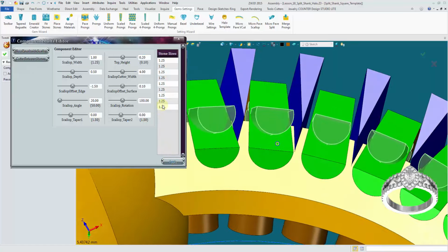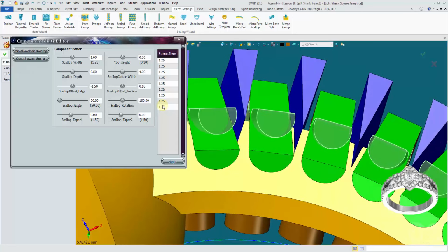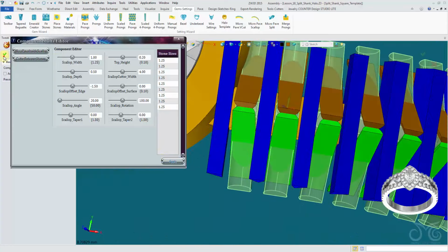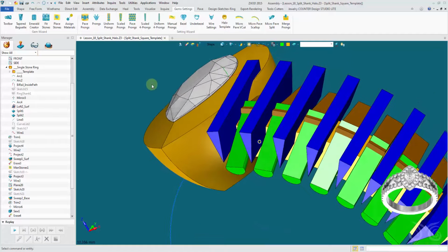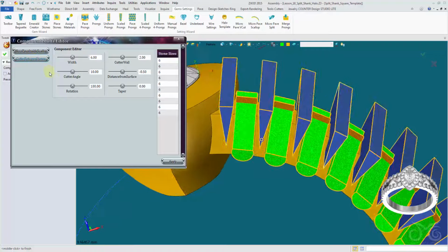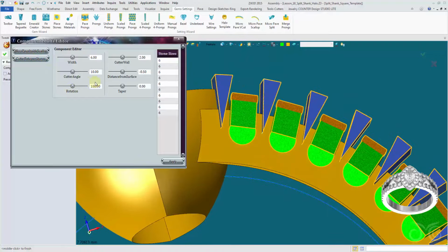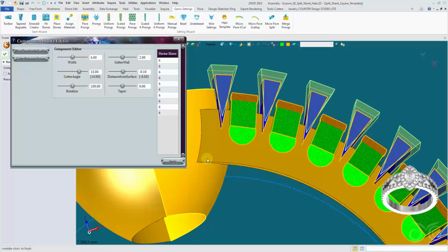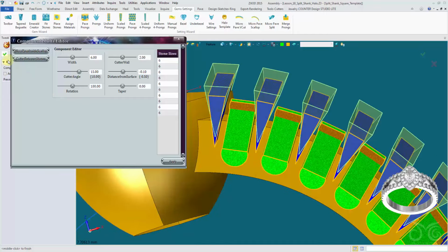Okay, the surface offset, I'm going to drop this down to 0. Okay, confirm, we'll start off there. Middle click to bring up the tweak again, pick the feature, now we're tweaking the cutters. This one, I'll just make my usual modifications, reduce the distance and increase the cutter angle. Confirm.